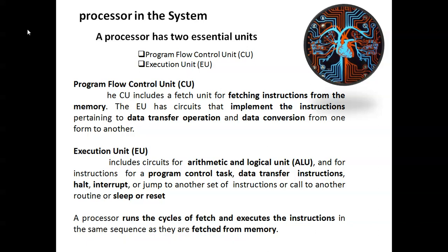These operations come under the execution unit. So the cycle: fetch and execution of instruction. The processor runs the cycles and fetches and executes the instructions in the same sequence as they were fetched from the memory.